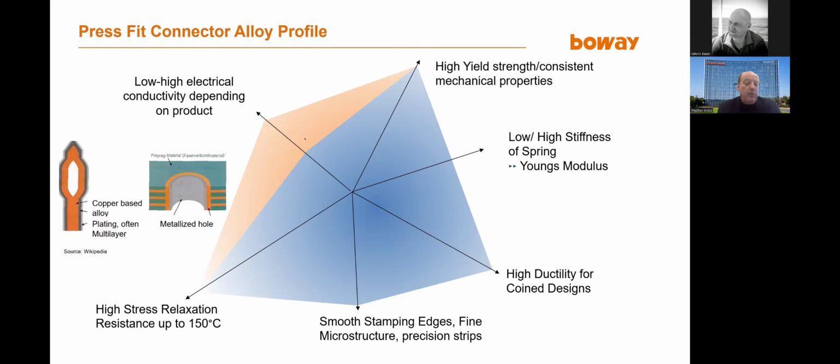This could be achieved, for example, with a certain microstructure. And here, especially bronze materials are dominating a bit, because with naturally hard materials, we can influence the microstructure quite nicely. So, the materials again range from bronze towards the high performance materials, depending as well on what kind of conductivity level or strength level you require.